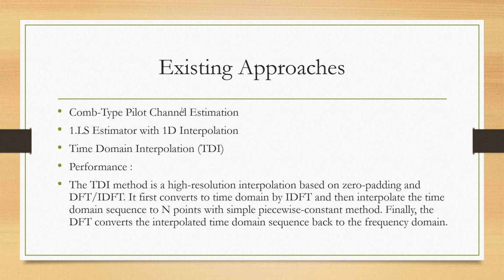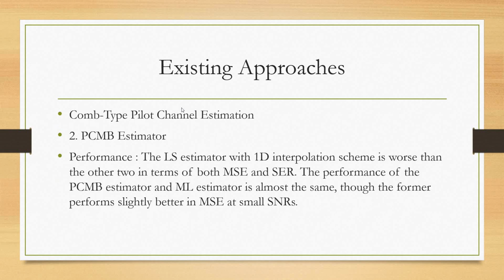And the performance of time domain interpolation is that it can provide high-resolution interpolation based on zero padding and DFT. It first converts to the time domain by IDFT and then interpolates the time domain sequence to N points with a simple piecewise constant method. Finally, the DFT converts the interpolated time domain sequence back to the frequency domain.